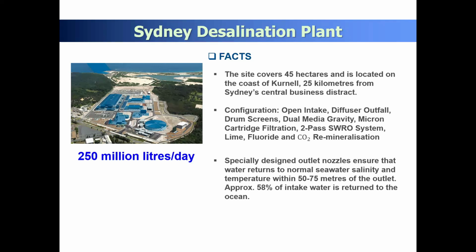The process is intake, diffuser outflow, drum screens, dual media gravity filtration, micro cartridge filtration, two-pass reverse osmosis membrane, and lime post-treatment, chloride, CO2 remineralization.